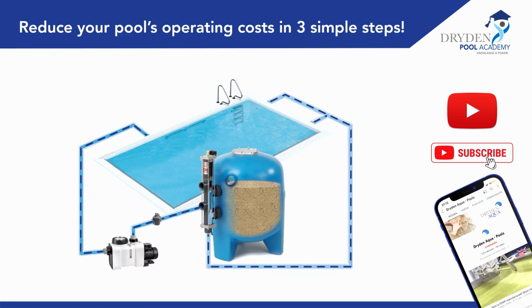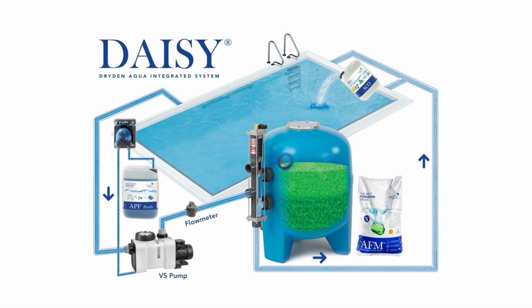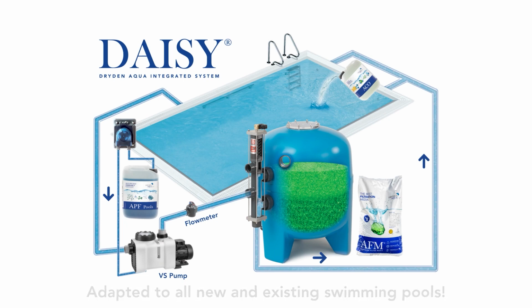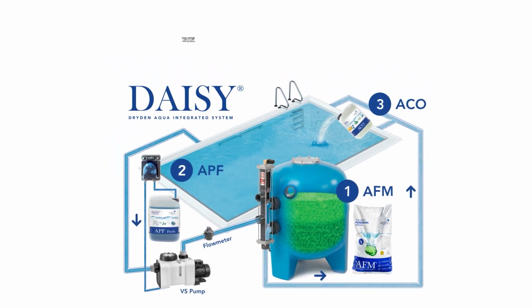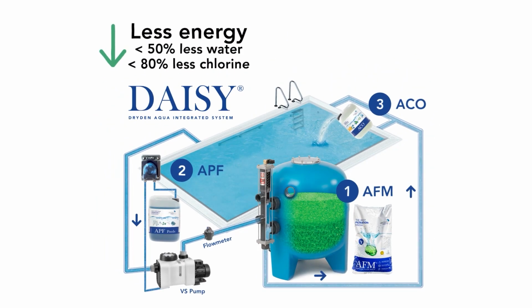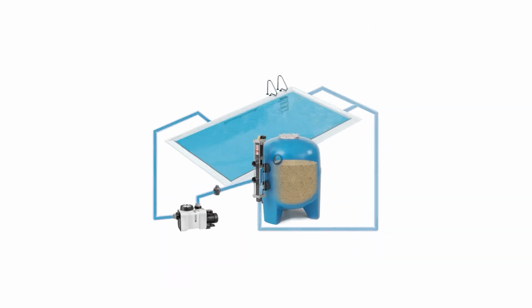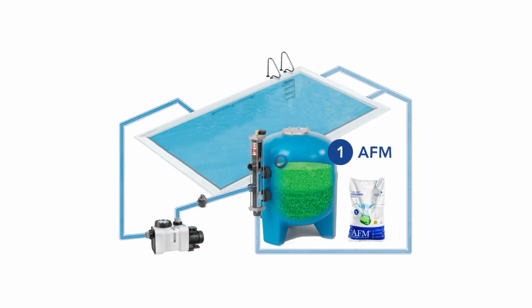To make swimming pools of the future more environmentally friendly, Dryden Aqua has developed DAISY, a unique and affordable biological approach adapted to all swimming pools' water treatments. In 3 simple steps, you can convert your pool to a DAISY pool to significantly reduce its operating costs, water and chemical consumption, and improve its water quality. How does it work? Step number 1. Replace your sand with AFM activated filter media.